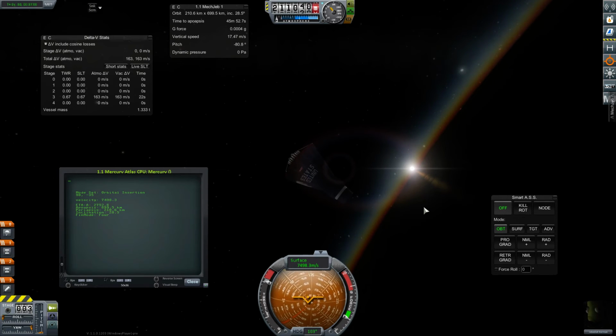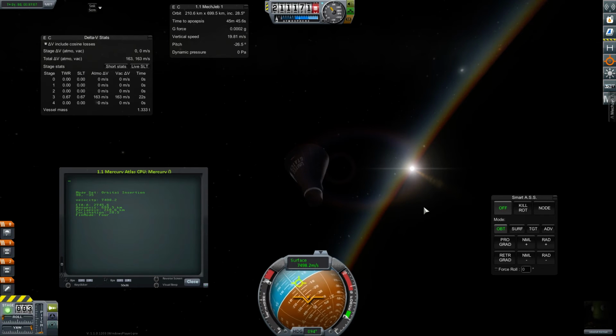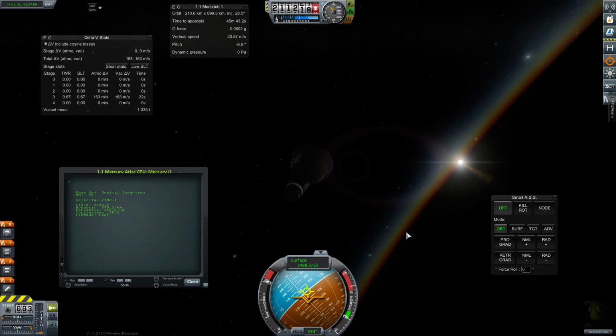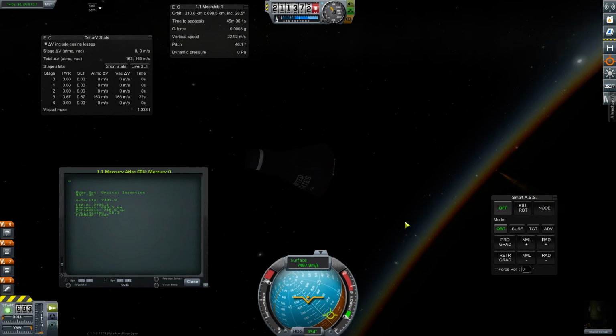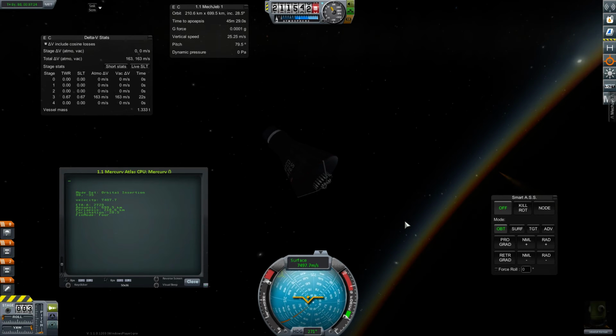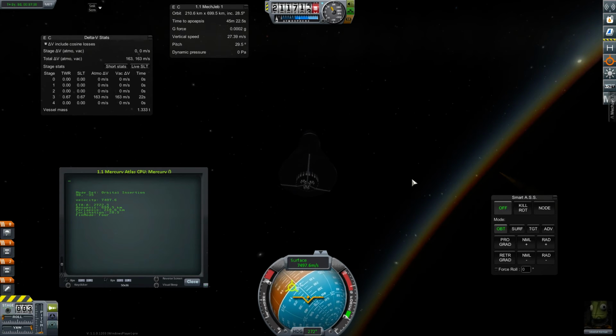It's pretty much just stripped down to the necessary little bits, the raw elements needed for this program to function successfully. And I'm going to be improving it. So the next thing that I currently have on the docket for improving this program, which has been on my docket for a couple weeks, I just haven't had the time, is to go from that piecewise function, where the pitch is just discrete outputs, where it just makes a discrete logic judgment and says, okay, that means the pitch should be -15 or -5 or 0 or 5, etc.